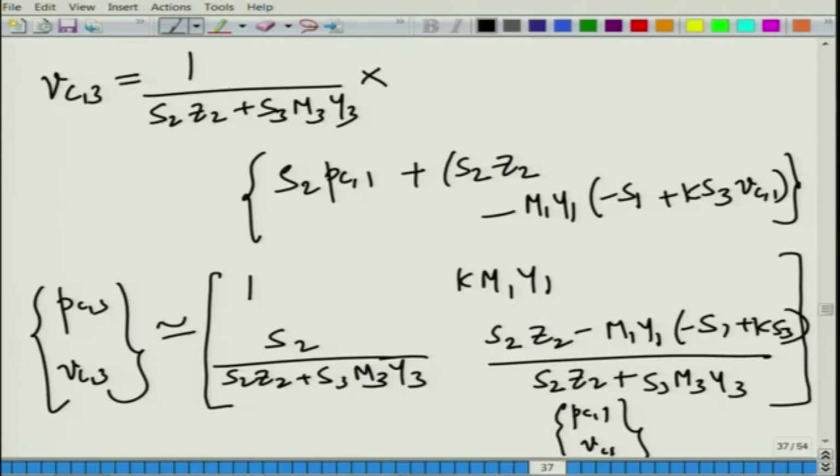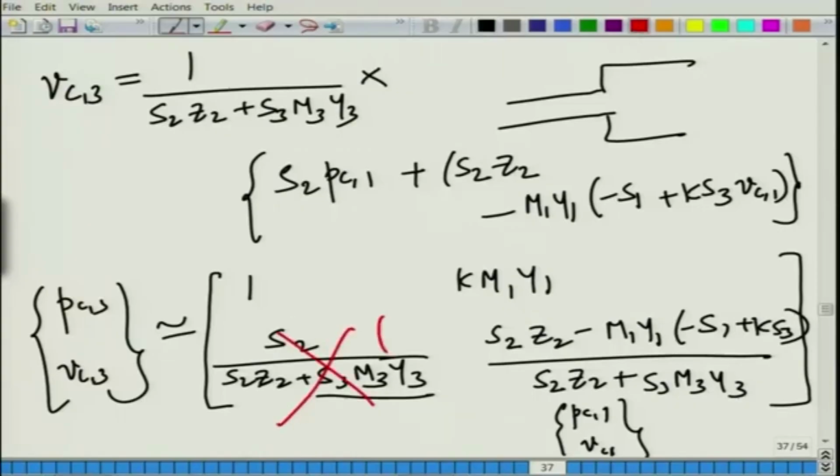There are a few important cases or corollaries that we would like to note here. When we have this particular thing, okay. Now, what happens if your inlet pipe is flush mounted? So, basically impedance right here, that is cot k naught L, L is 0. So, cot at 0 is tending to infinity, is it not? This is going to infinity, and this is tending to a very large number, and so all these terms are very small in comparison. So, basically the result will be that this will be 0, okay.